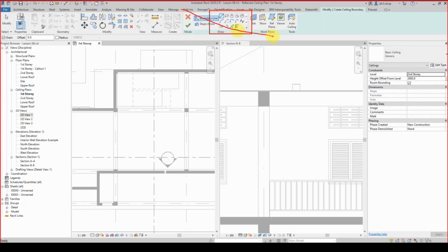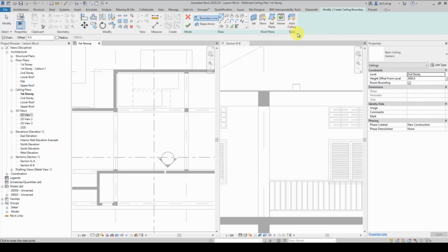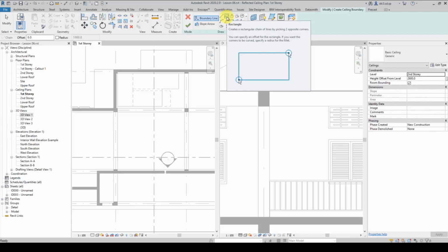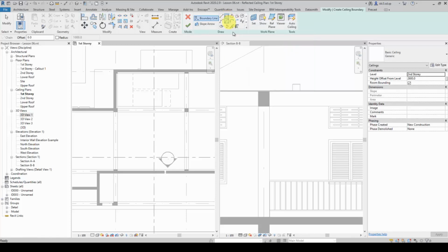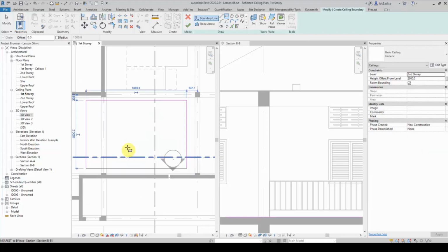I'm just going to select this element here and go back to the sectional view down here. You notice there is a blue colored line being selected here. That is the ceiling element itself. But my display option is correct and it shows hidden line. So why do I still see the beams and the ceiling board together? Technically speaking, if I have created it properly, the beams should have been behind the ceiling board.